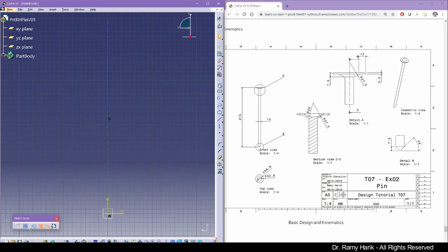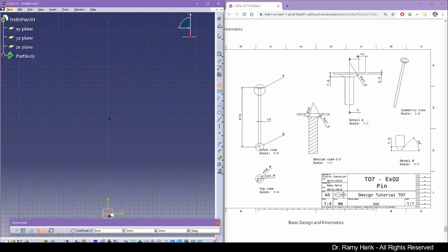Now let's go ahead and click profile. You know by now this is my favorite button to actually work with. So now we're going to create something that is approximately 45 degrees. You can see the angles from here. So 45 degrees was approximately a height of 7.5. So that's good enough. Then we're going to go up all the way, approximately 400. Of course, we're going to put dimensions later. Then we're going to start creating this circle here.